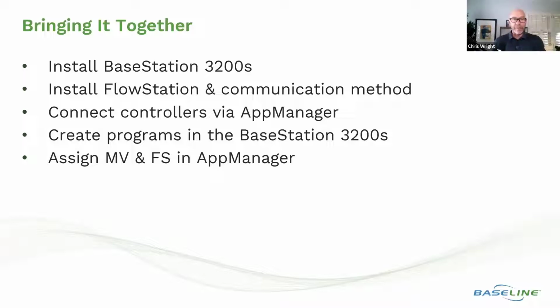Yeah, and Andy, it brings up what we were talking about earlier: the 3200 itself is very powerful in its capability, both programming and support, but it requires another algorithm in order to manage the design flow for multiple controllers that may be on a hydraulic structure. And that's where the FlowStation is needed, because it has a different operating algorithm coded in it that helps to manage that. Yep, different algorithm. It's powerful, and requires more horsepower than one single controller is capable of doing.